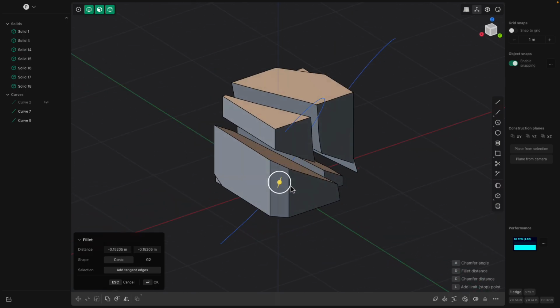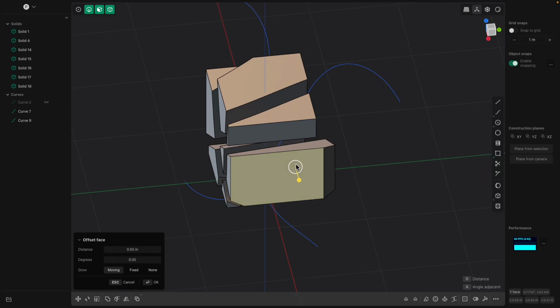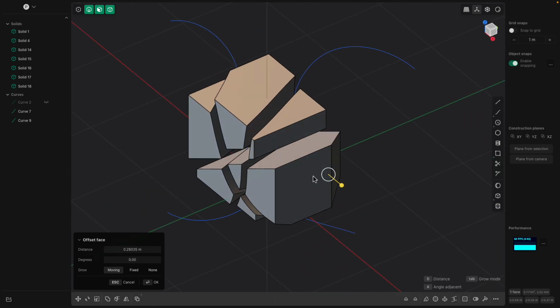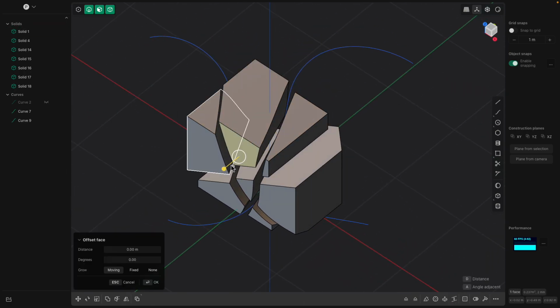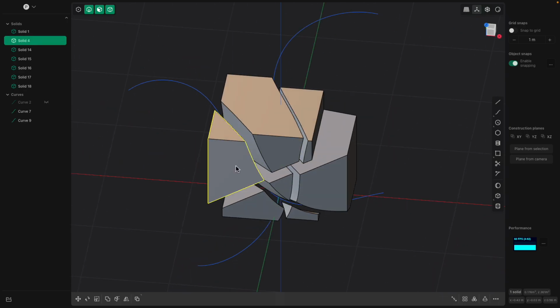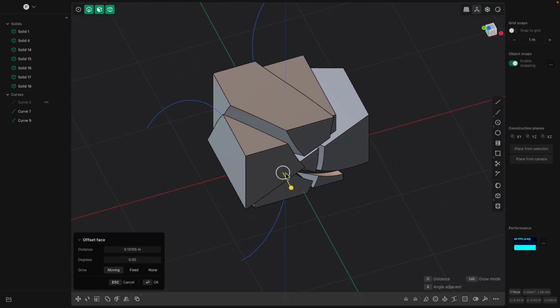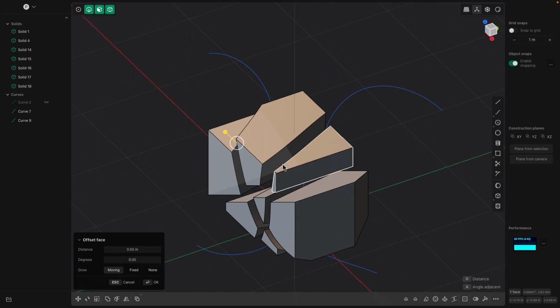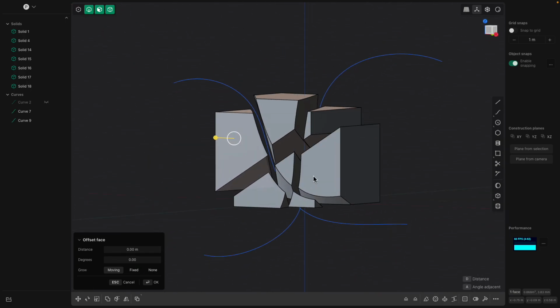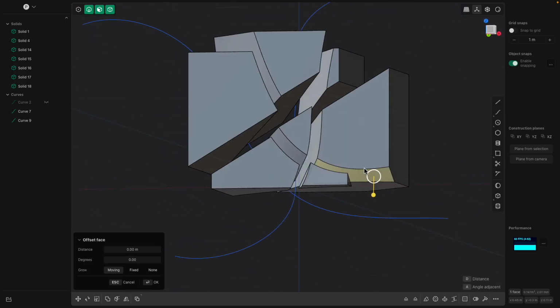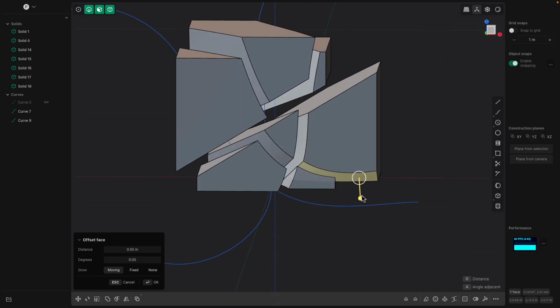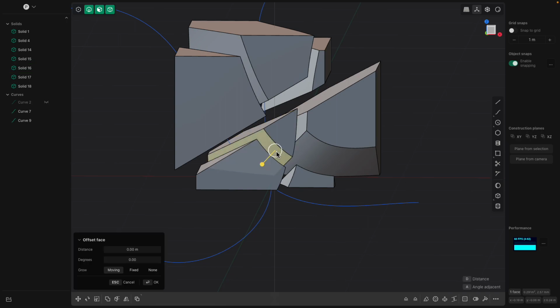Remember, you can still do bevel and things like that. Yeah, all the extrude, everything still works, including the part that, if you cut it with a curve, like that curve angle, you can actually push and pull that area.